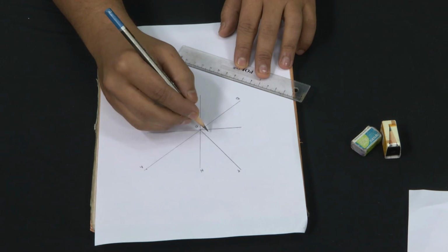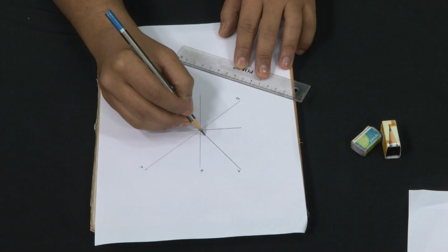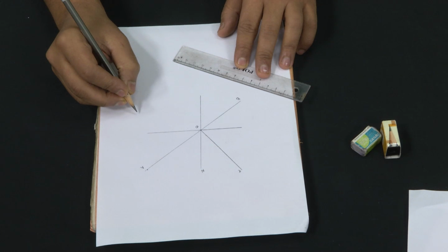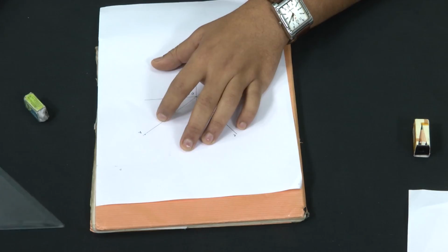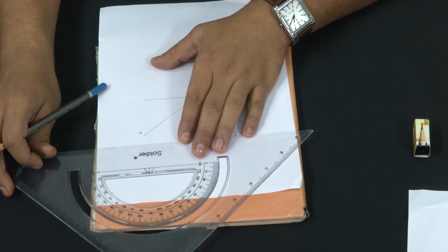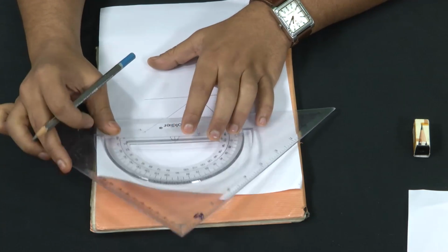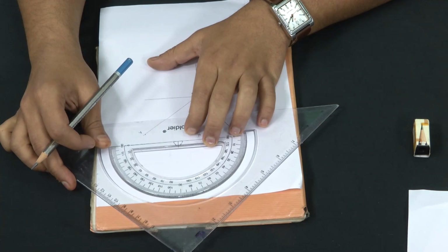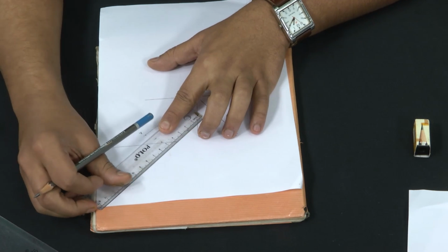Now, to find out the point corresponding to the 100 meter strike line or stratum contour, we know that the dip of the bed is 48°. So, what we do is that we first draw a line over here. We now construct a subsidiary diagram where I draw this line. Now, I mark the 48°. So, in this diagram I join these two.